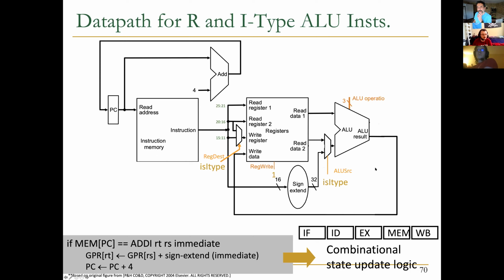How about adding one another ALU, right? Okay, ALU 2, okay? And then we get rid of this. We send here, and then we send this into here, okay? Does that work? But obviously we send the right wire back as well. So we use this ALU for R type. We use this ALU2 for I type, right? Because we essentially need the same operation.